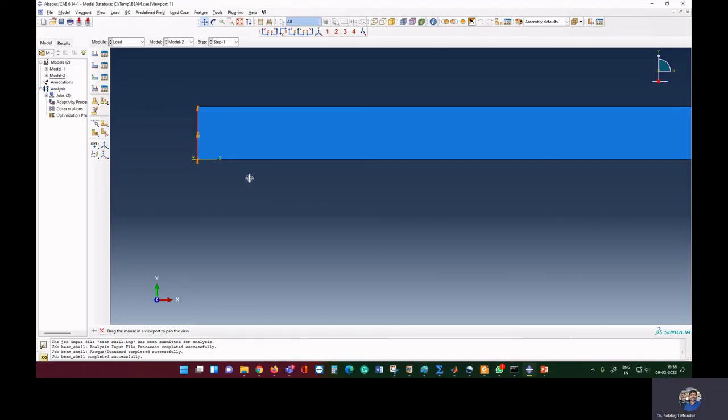If you make the geometry in the xz coordinate, in that case theta z should be 0. But here we made the geometry in the xy plane, so we'll have rotation theta y equal to 0, and our vertical displacement is 0. That we'll see how we can do. So we can check at what condition we can give.